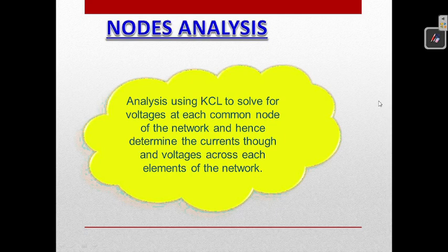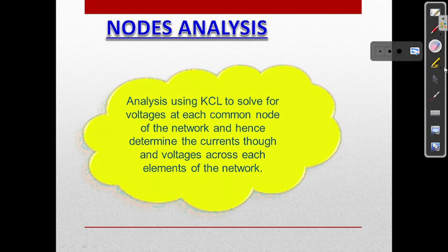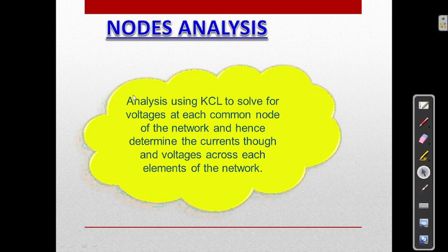Good day to all. Today we are going to see nodal analysis. This is for Kirchhoff's current law. Analysis using Kirchhoff's current law to solve the voltage at each common node of the network and hence determine the current through and voltage across the elements of the network.